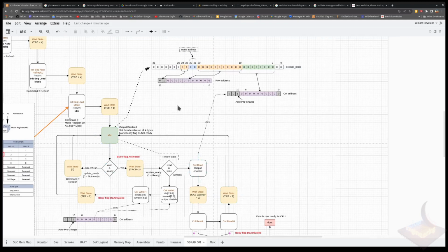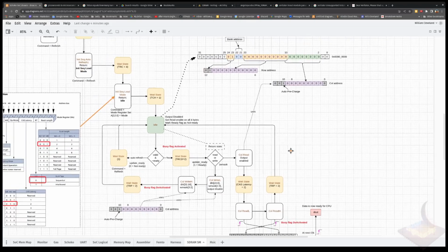And the same thing for the reading here. We're going to look and pull out of the actual address all the data and place it into the top. Again, we don't need to look at the two lower bits because we're word aligned on everything here. So we don't need that. We'll take these bits and put it in here, and the top two, which in our case will be the 8 bit right here. So there's 1, 2, 4. We're at 4,000, sorry. The RAM is at 4,000. We'll put it into there, and then it'll go through the read sequence and come out.